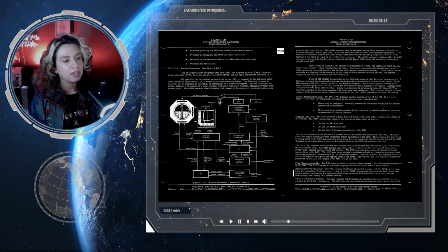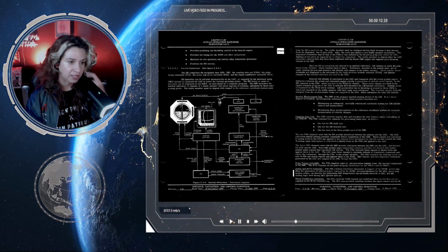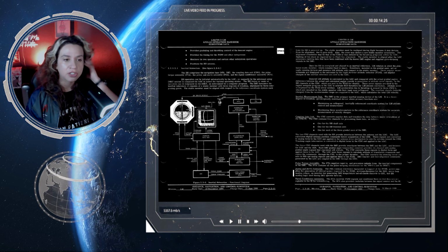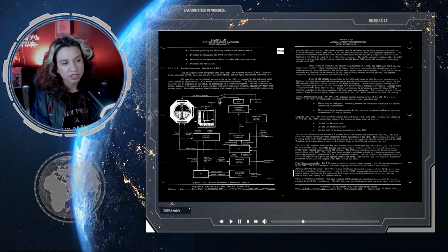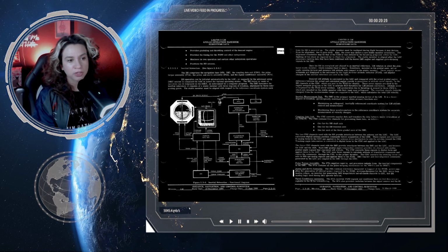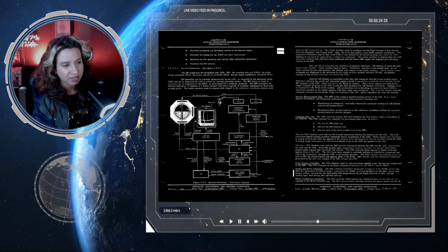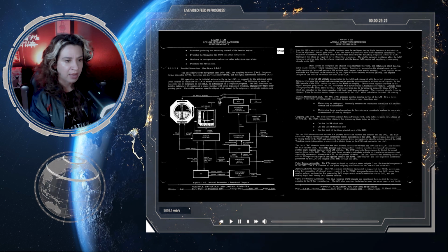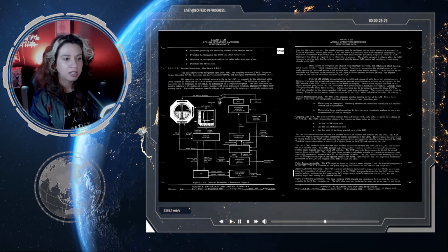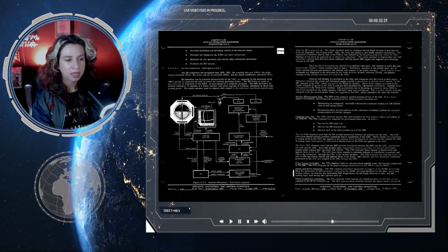The 3 CDU channels used with the IMU provide interfaces between the IMU and the LGC, and between the LGC and the AGS. Each IMU gimbal angle transmitter resolver provides its channel with analog gimbal angle signals that represent the LM attitude. The CDU converts these signals to digital form and applies them to the LGC.